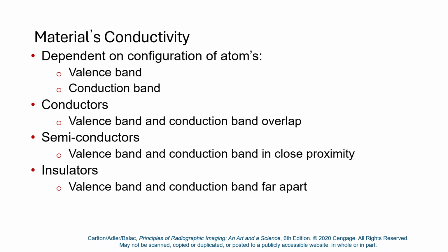All right, so a material's conductivity is largely dependent upon the valence band. Does it have just a few loosely bound electrons, like copper? That's great. That's perfect, in fact. Is the conduction threshold, that is, the ability of the electron to wander free, something that takes a great amount of energy to get it out of the valence band? So the difference between the binding energy in the valence band and the energy threshold for the electron to wander free.